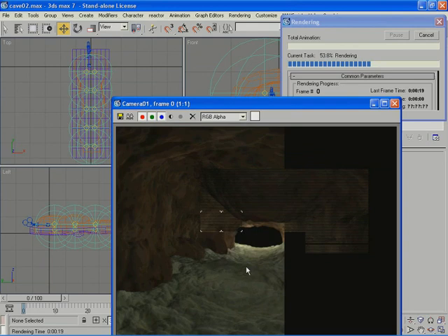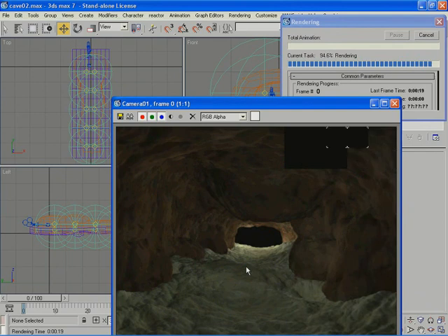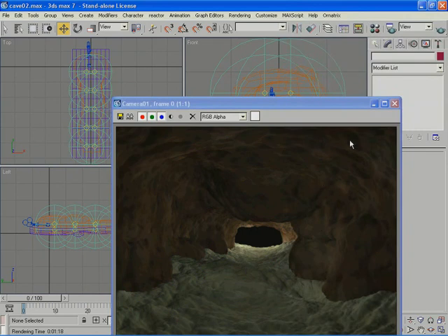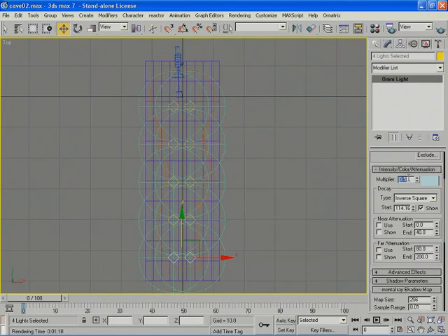And for now, all that's left for me to do is change the color and fine-tune the multiplier of the different lights that I have. But my setup is good, and I'm getting this result without actually using shadows, which would first of all speed up the render time. And this contrast is obtained because I used decay, which would create a volume inside which I'm going to have the light affect my region. So what I will do now is select these and set the multiplier maybe to 0.8. Select those and set it to 0.4.